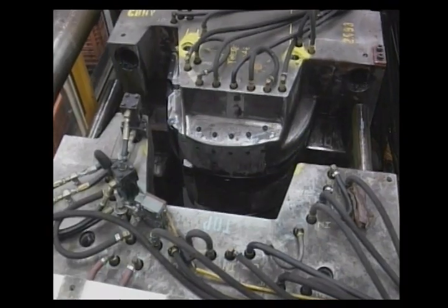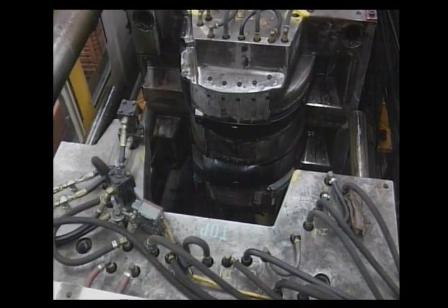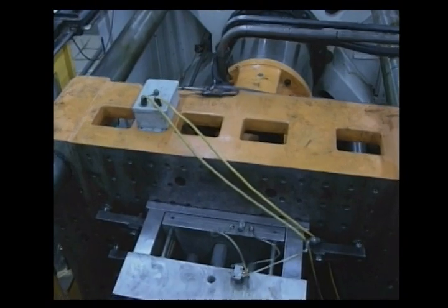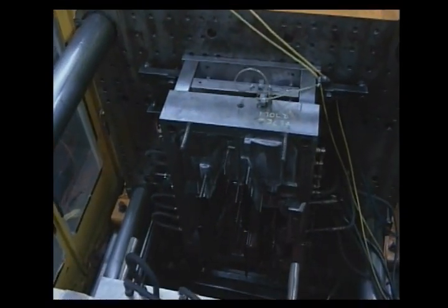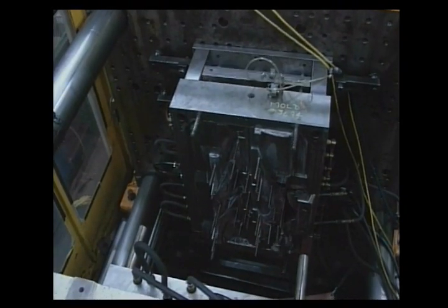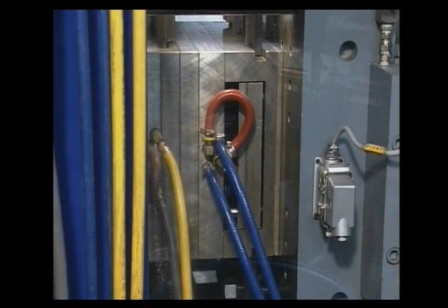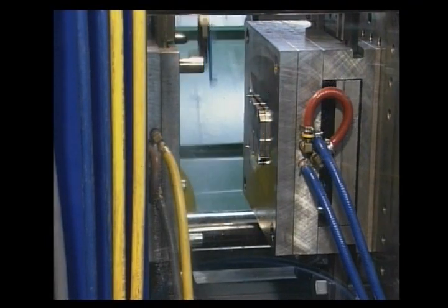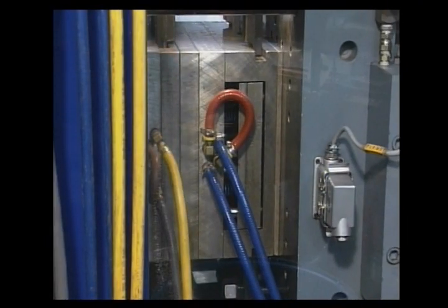Since the force of the molten plastic against the mold creates significant friction, a knockout system is required to aid in part ejection. This is usually in the form of knockout pins. In some molds, a sprue puller aids in removing the molded plastic from the sprue. This material can then be reground for reuse.